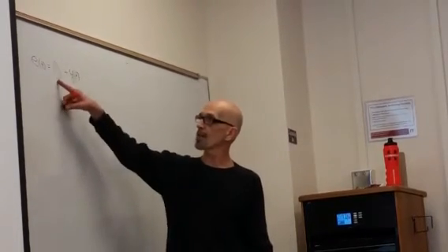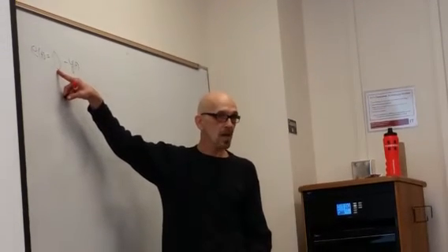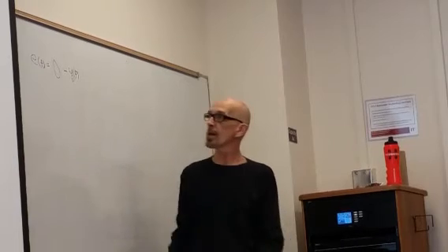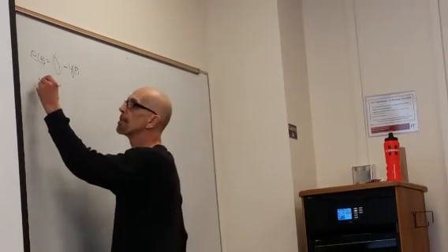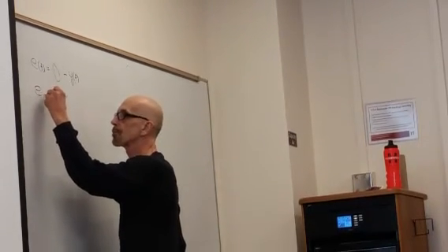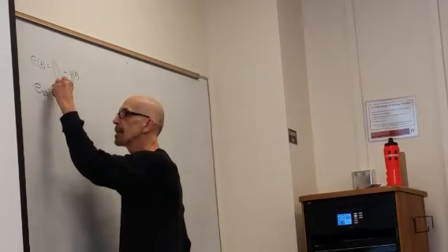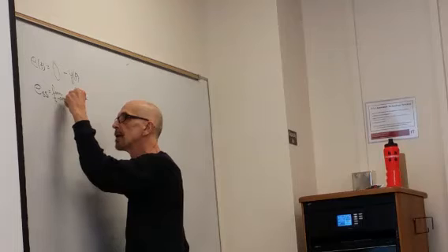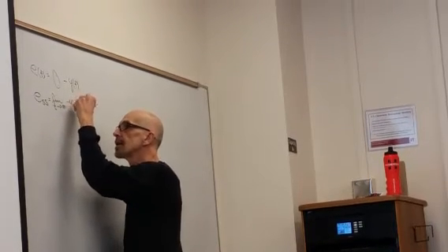Remember, for a command system, it's y sub c, the command, right? There's no command here. It's a disturbance. So, E steady state is the limit as t goes to infinity of negative y of t. Correct?